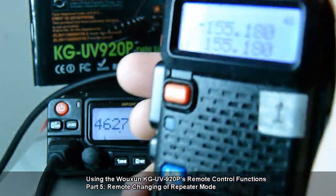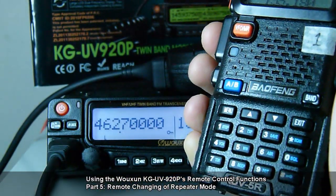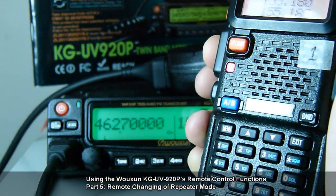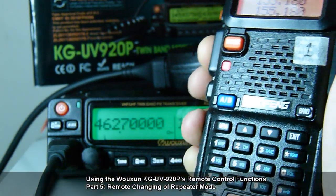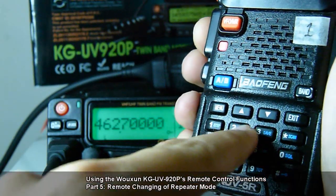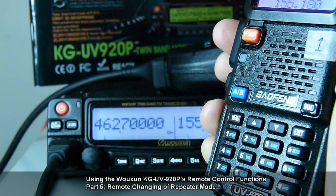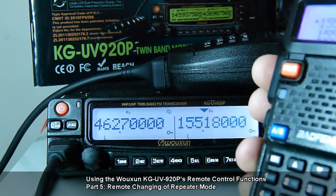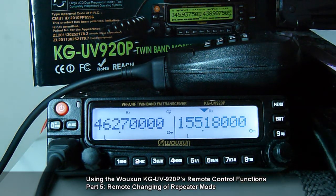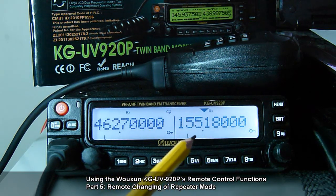Then there's that beep heard on the HD controller, and then within 30 seconds you hold the PTT again, and then you do 0, 3, and then 2, and release the PTT. Then what follows next is that the KG-UV920P would reboot, this time to directional crossband repeater mode.